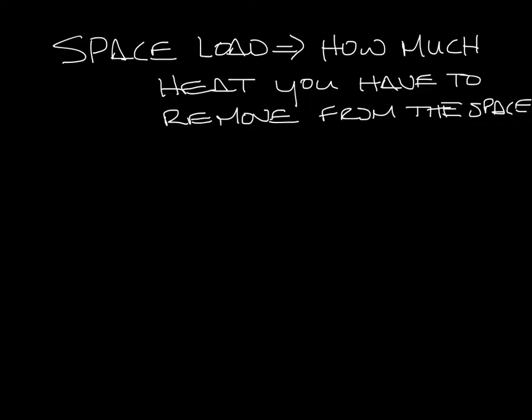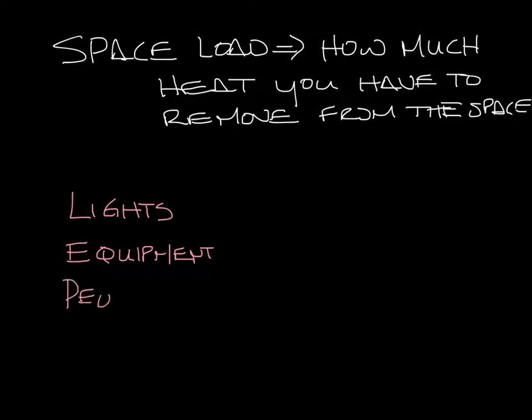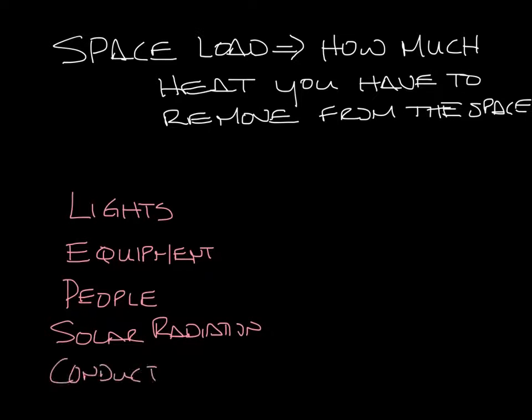There are a lot of things in a building that contribute to the space load. The lights in the space, computers and other equipment in the space, and people in the space. You may also have a solar load coming through windows, or conduction coming from the outside of the building.